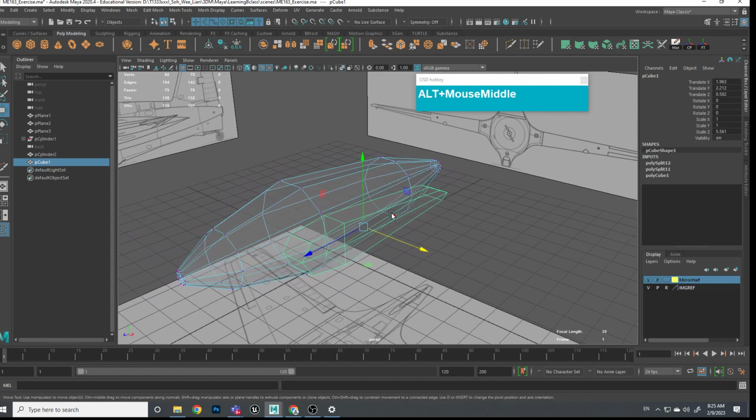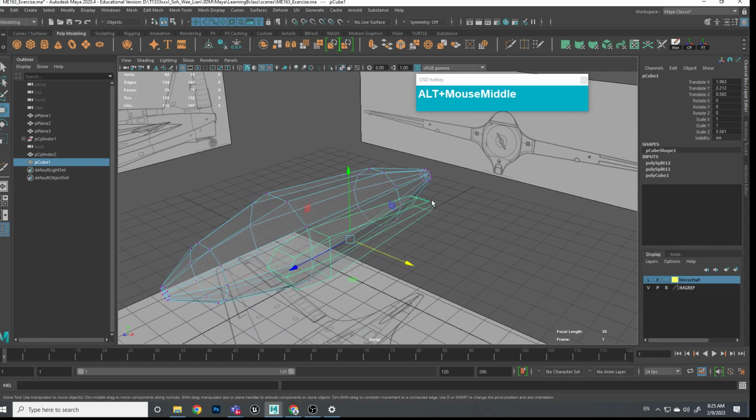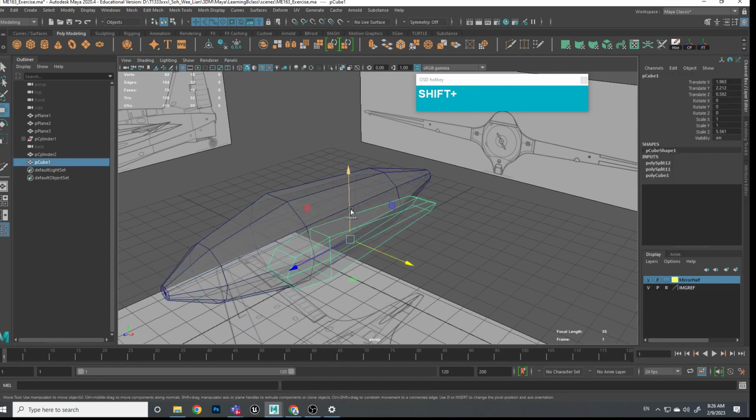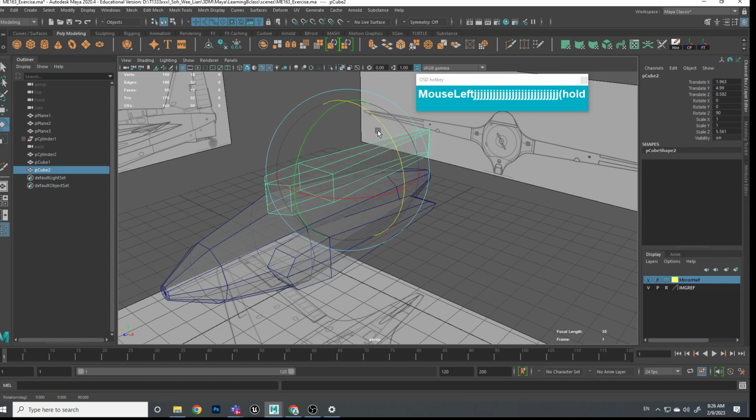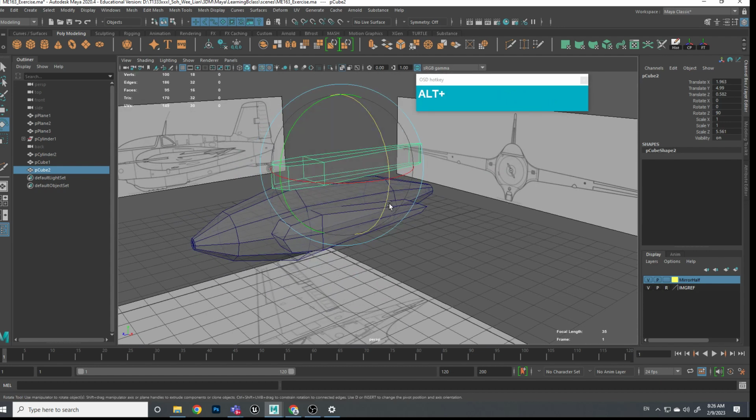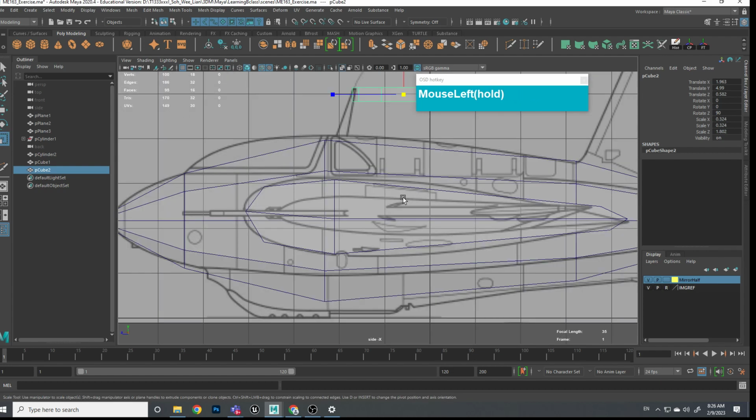Remember just now that video was saying, I'm going to reuse this shape for my vertical stabilizer, or the tail fin, this part here. So to do that, I'm going to clone it. With it selected, holding down shift and move, grab the move arrow and you can clone. And I'm going to rotate this 90 degrees vertically. Holding down the J, rotate it 90 degrees like that. Scale it down.